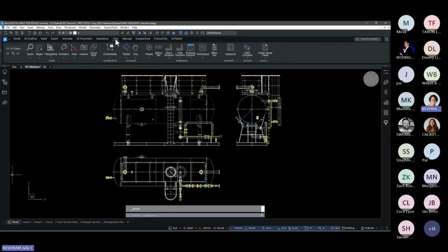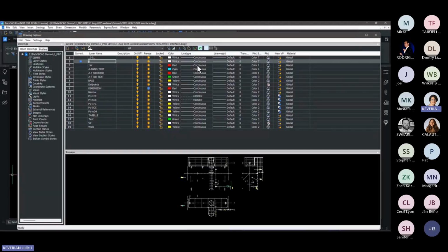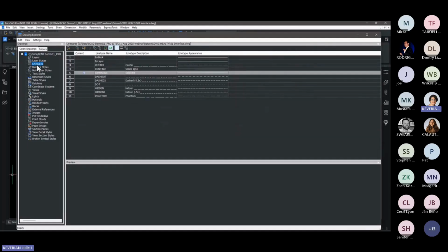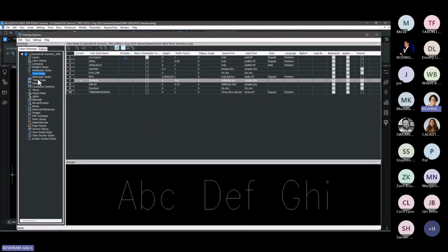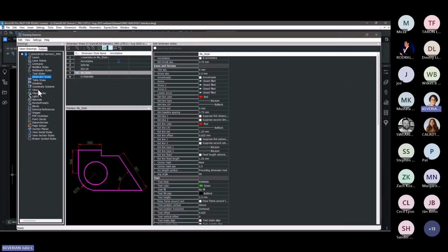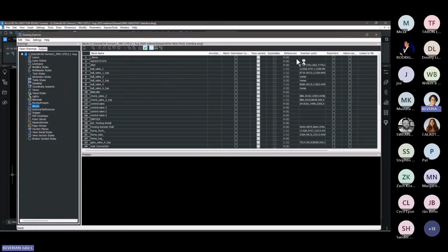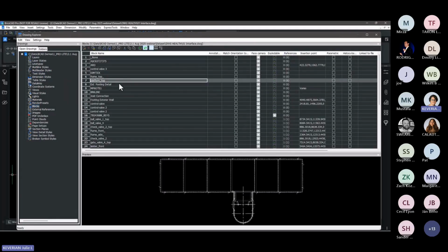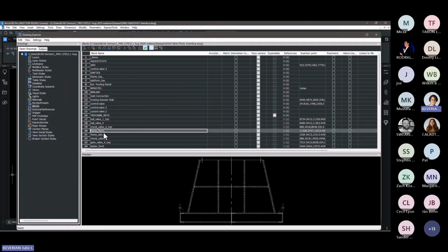What does that mean? Well, first, we need to understand what's in the drawing. And the Drawing Explorer organizes drawing content into groups like layers and styles for text, for dimensions, even page setups, and of course, blocks. Now, in this particular drawing, we've got quite a few block definitions with 0 block references. That means the blocks have not actually been inserted into the drawing.